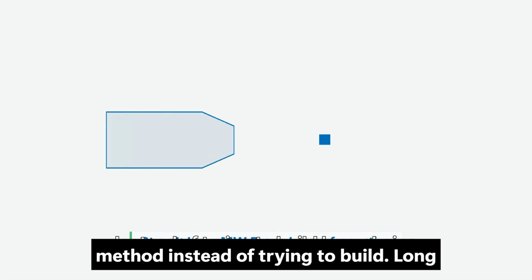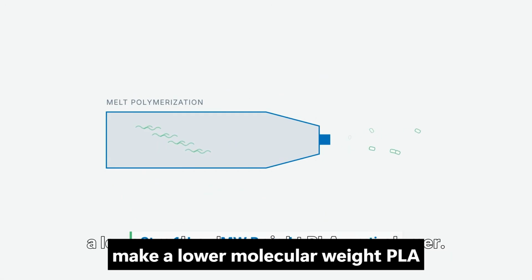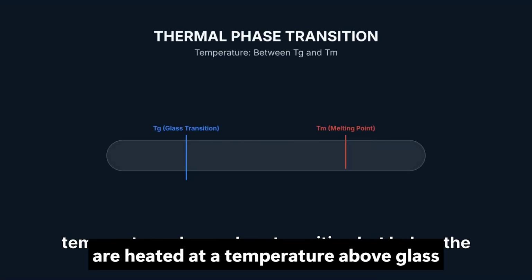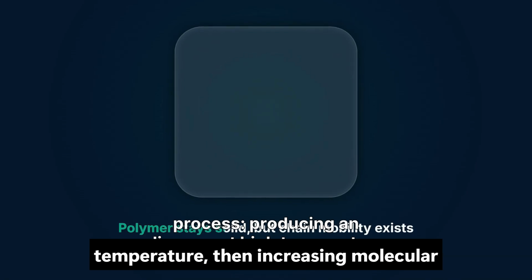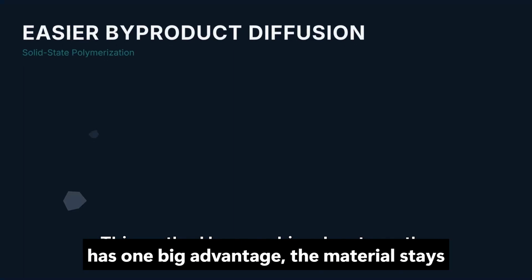Solid-state polymerization, or SSP, is a clever method. Instead of trying to build long chains in a viscous melt, engineers first make a lower molecular weight PLA prepolymer. This is then converted into powder or pellets. These solid particles are heated at a temperature above glass transition but below the melting point. A review describes SSP as a two-step process, producing an oligomer at high temperature, then increasing molecular weight in the solid state.